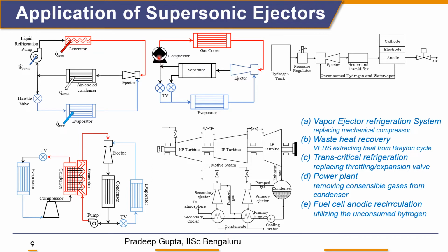The vapor part is sent to the compressor, and that rejects heat to the ambient in the gas cooler, while the liquid part is sent to the evaporator after expanding in the throttle valve. In this case, the throttle valve sees a very low pressure ratio. That is why the irreversibility decreases. The other throttle valve here has been used just for the mass balance.